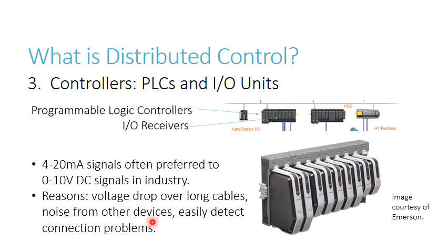There can be noise from other devices on the line. Now, that's a problem for voltage. At first, when I saw that, I thought, if the line has such and such an impedance, and there's noise in the voltage, shouldn't there also be noise in the current? But really that's not the case, because the transmitter that's putting out the 4 to 20 milliamp signal is like a constant current source.